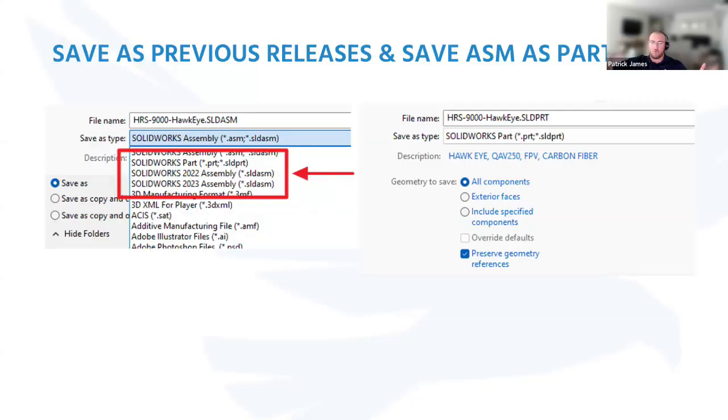If you have someone working even older or you don't want to use this feature for whatever reason, if you're going SOLIDWORKS to SOLIDWORKS, I would recommend saving as a Parasolid. Basically it just strips out your feature tree, but all the solid data gets transferred over. Reason being, Parasolid is the kernel that the SOLIDWORKS files run on, so it doesn't have to do any translating. So that's really the best one for SOLIDWORKS, but going to outside of SOLIDWORKS, you can use all the regular ones, Parasolid, Step, IGES, they all work fine.